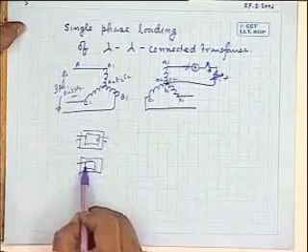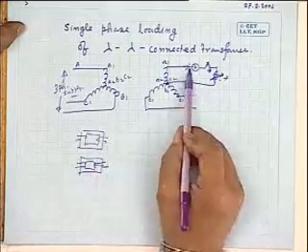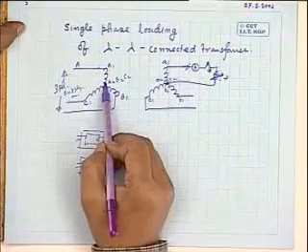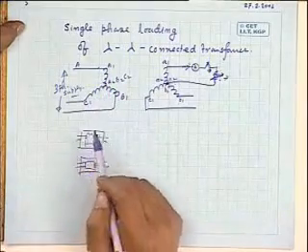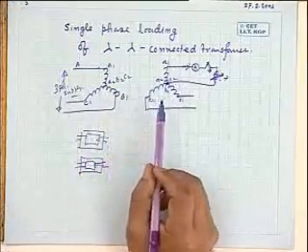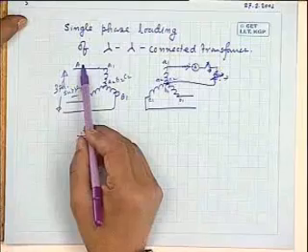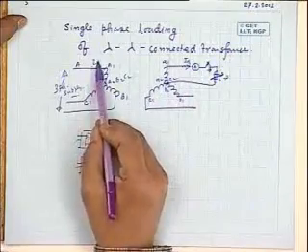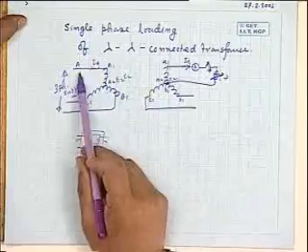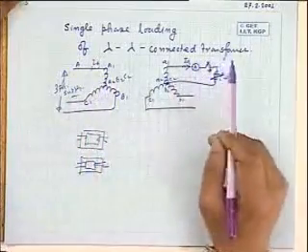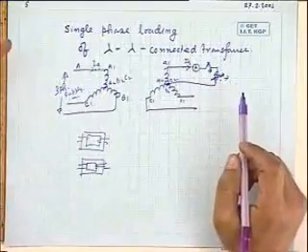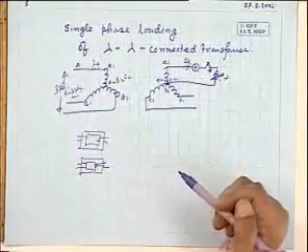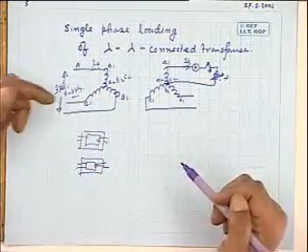The flux like this, 3 transformers are there. Now the point is, if you load the secondary of a phase, there must be additional current drawn from a phase here in order to keep the flux in its core constant, MMF balance. Suppose it draws that current. Some current IA flows here, it draws additional current IA by its turns ratio, etc. But this current has to go back to complete its path on the primary side. How can it complete? There are 2 ways out. It will go like this and this, it will divide through the B and C lines.